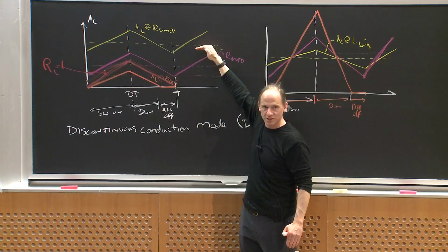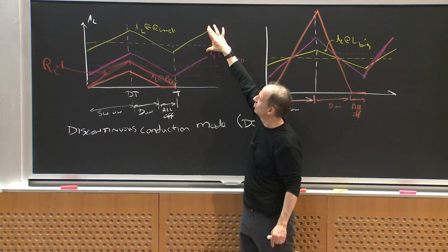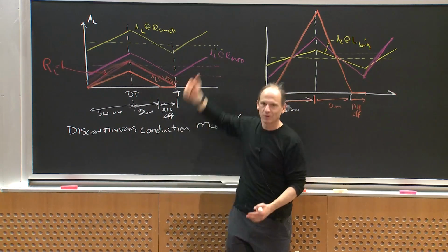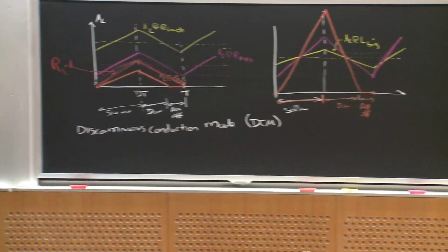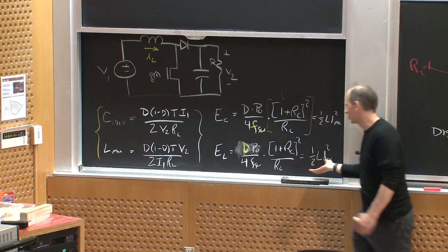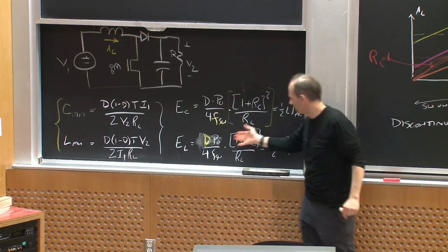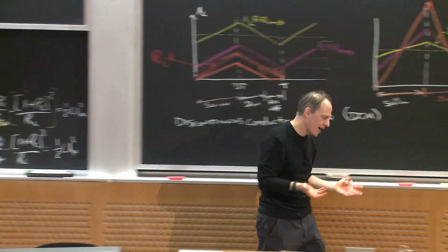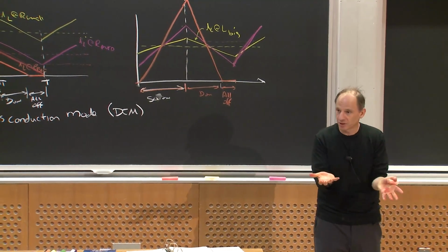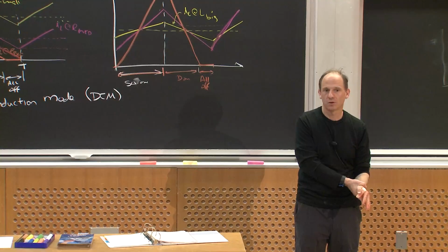Well, if you have to deal with a very high load resistance or a light load, that means your average is going to come down and down and down, and the only way to keep it in CCM would be to use smaller and smaller ripple so you never hit that mode. And the only way to do that is to get a bigger and bigger inductor. But you've got to run at high load too, and if you've done that with a much bigger inductor, suddenly you've got a lot of inductor energy storage. If your ripple ratio is small at light load, it's really tiny at high load, and this factor will kill you. You'll just have way too big a component. So as a practical matter, if you're going to run over a really wide power range, you might have to deal with DCM. So we often design our converters for continuous conduction mode at full power, but they might go into DCM at very light load power. Any questions about that?